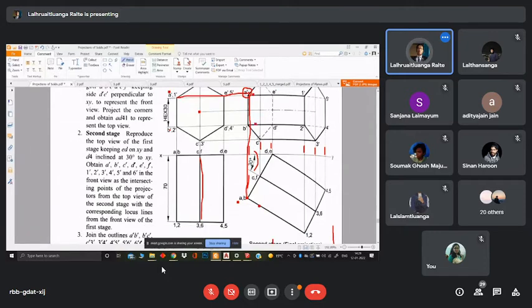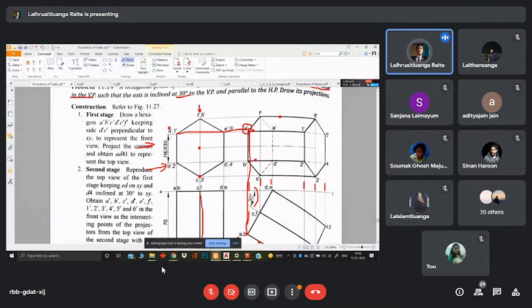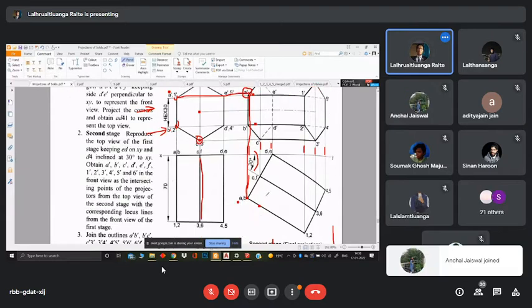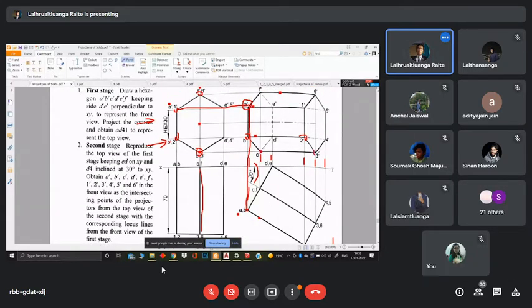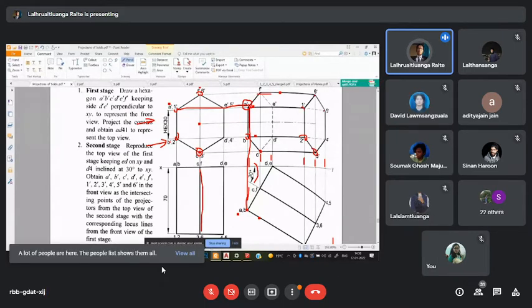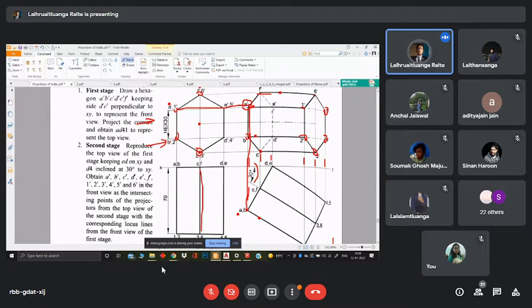And there is going to be a lower line, this part. So as we are looking from this direction, we will have this part, this part, this part, this part all visible. This is the top part, so they are also visible, and the invisible parts are joined together with dashed lines or dotted lines. It would be your choice.